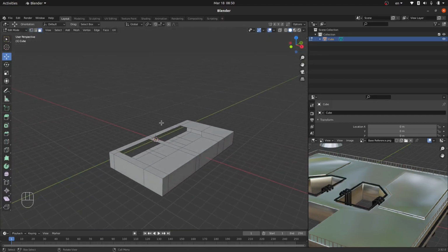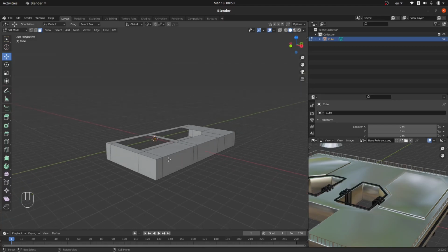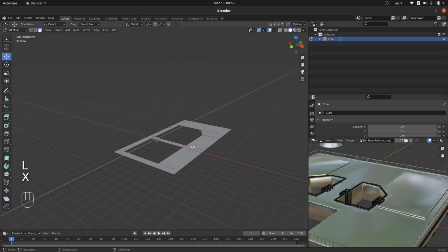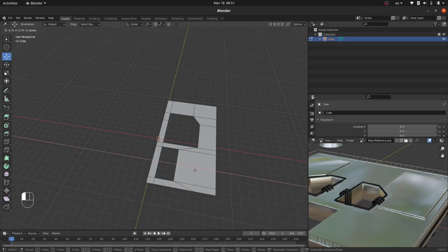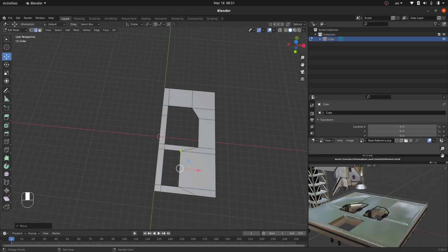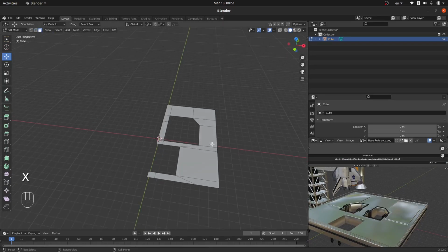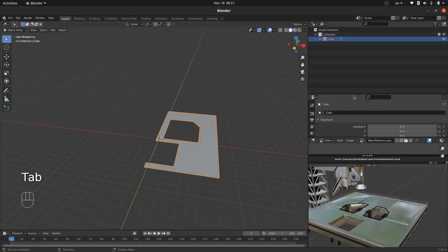And also, in order to be able to see them better, I'm gonna just delete the rest of our base. So L to delete the entire units, and after that we're gonna be extruding it. So over here I'm gonna be dragging this edge like this, dragging it to the left side, just like that. And also I'm gonna be deleting this extra face because we're gonna be adding that mirror modifier. You know what? Let's do it right now.